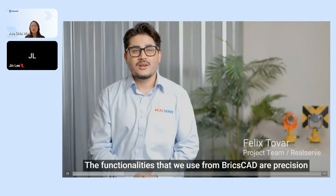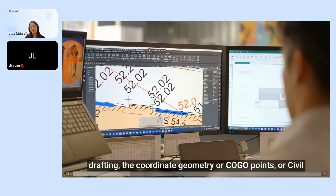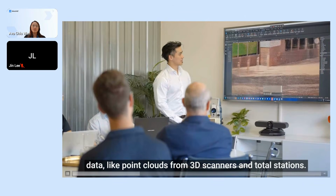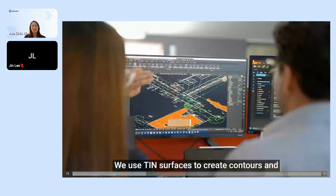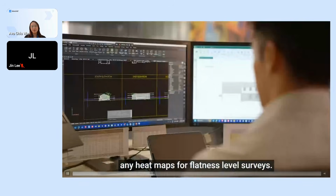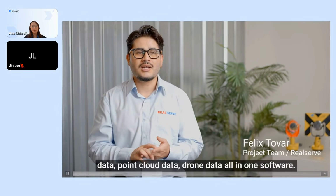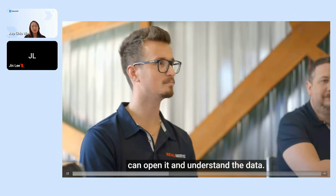The functionalities that we use from BricsCAD are precision drafting, the coordinate geometry or COGO points, or civil points as called in BricsCAD, and integrated external survey data like point clouds from 3D scanners and total stations. We use TIN surfaces to create contours and heat maps for flatness level surveys. The biggest benefit is the fact that we can use total station data, point cloud data, drone data, all into one software. Everything is in just one spot and anyone can open it and understand the data.